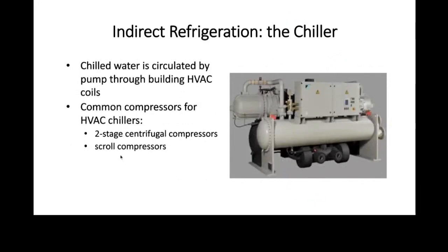With these chillers, this one here looks to me like it's a screw. I can't remember where I got that picture from. Maybe that's from York. Now, the evaporator is interesting. The evaporator here is all insulated, and anything that's under low pressure is insulated with this black insulation. You've seen this. Now, this here is the condenser, and you can always find a condenser because it's uninsulated, right?